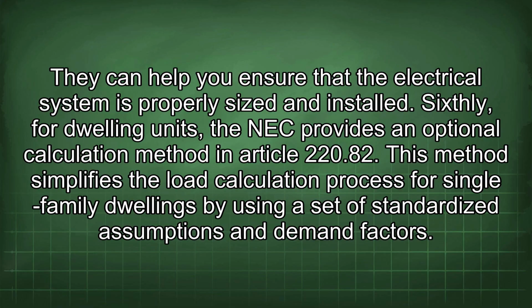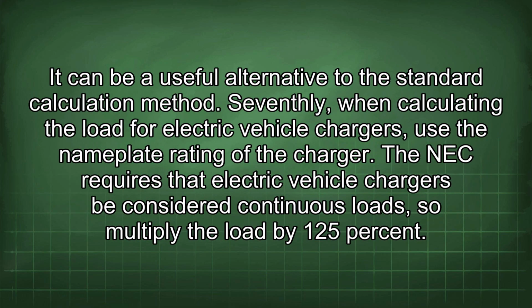Sixthly, for dwelling units, the NEC provides an optional calculation method in Article 220.82. This method simplifies the load calculation process for single-family dwellings by using a set of standardized assumptions and demand factors. It can be a useful alternative to the standard calculation method.